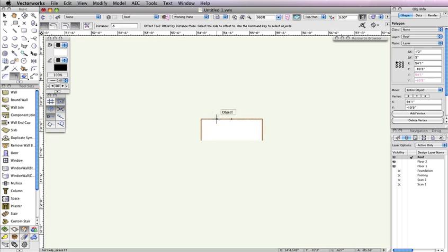To add a little more detail to the profile shape, let's select the Reshape tool in the Basic Tool palette. Enable Add Vertex mode and Corner Point mode in the toolbar. In the drawing area, click once on the bottom right vertex of the polygon. This will add another vertex point to that polygon. To set the exact placement of this vertex point, press the Tab key to enter the floating data bar. After doing this, you should be able to edit the length field.